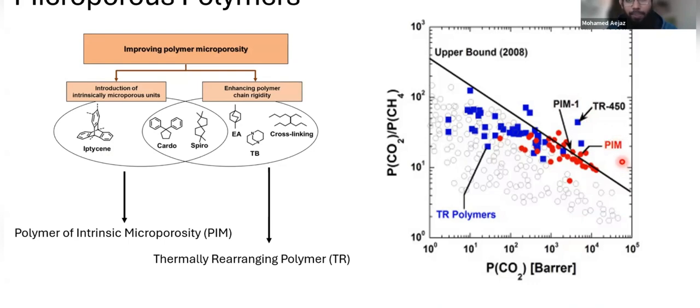So I showed you two approaches, right? One is you add a nanofiller to your polymer, and then you have enhanced gas permeation. Or you make a polymer that has too many benzene rings or too many cyclopentane rings, such that they pack so inefficiently that you have holes in your polymer, and then you use these holes to transport gas, and that also results in better properties.